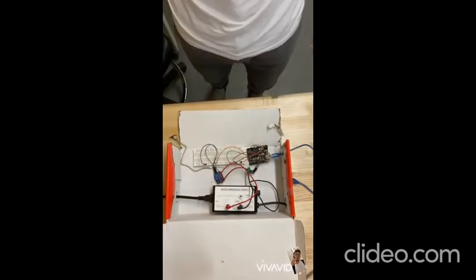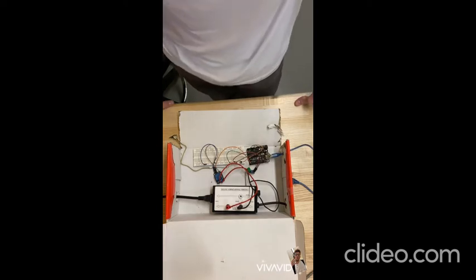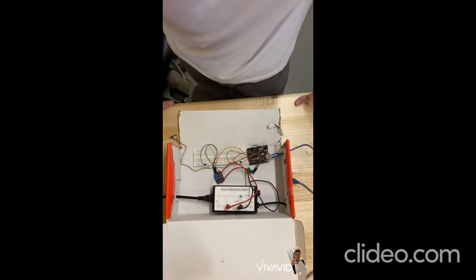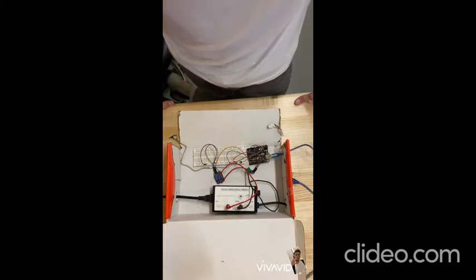Yep, this way we can notice that the heater is starting. The heater turned on when we plugged the transformer tester onto the wall, which proves that the relay and the current sensor are working fine. And the next step, I'm going to go through my code and test it to see if the code is working and the specification is correct for the circuit.